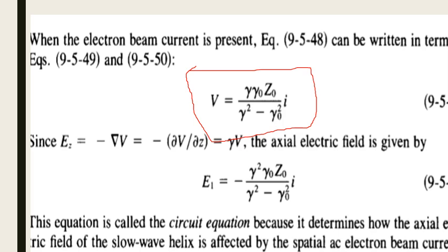So don't get confused, because of your helical structure, the electron movement behaves in a different manner. It induces its own current, and because of that, you have an extra component of gamma also coming into the picture. If you have an extra component of gamma also coming into the picture, can I say alpha is already not there, because we say attenuation is very minimum. But this gamma will definitely give rise to more beta values now. So these more beta values we will try to find out.